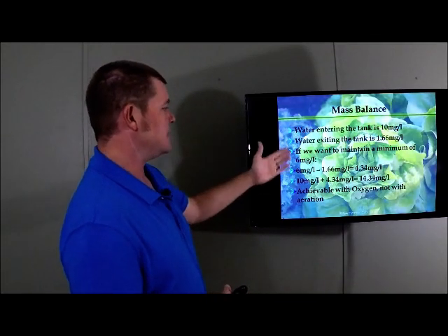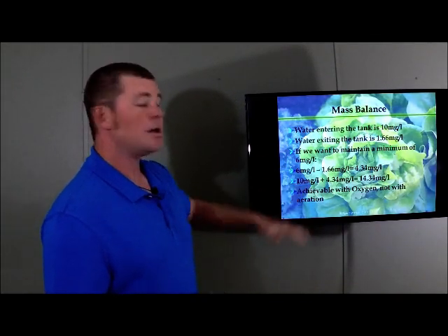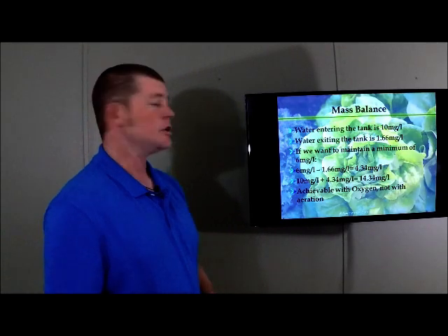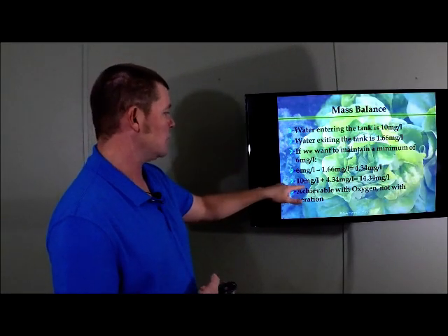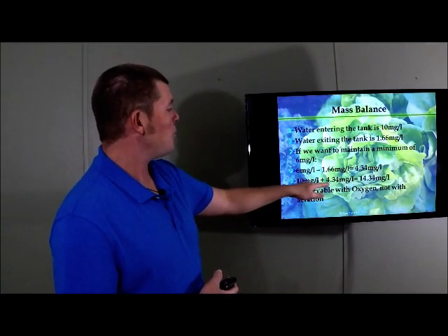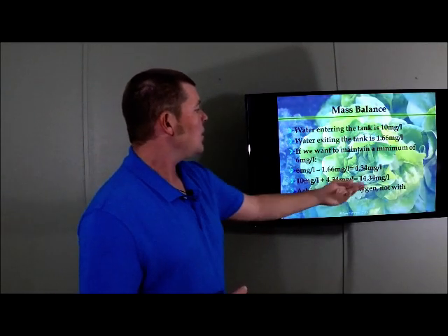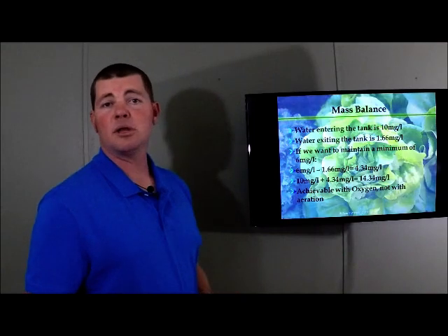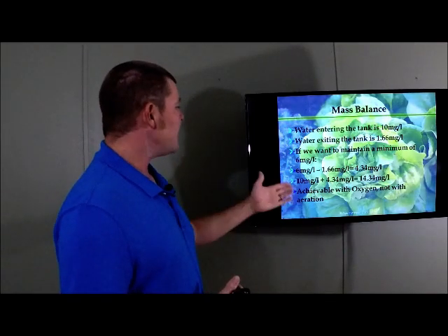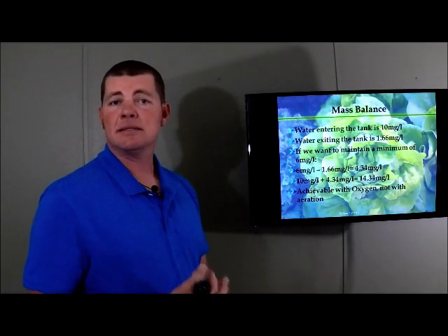That's the deficit there. We add that to our incoming water concentration. It's coming in at 10 milligrams per liter. So if we add the 4.34 milligrams per liter that we have calculated, we get 14.34 milligrams per liter. That is what we want to inject into the tank.